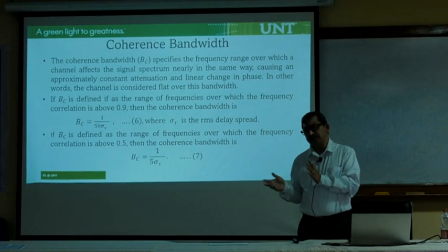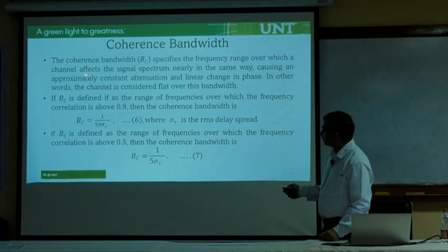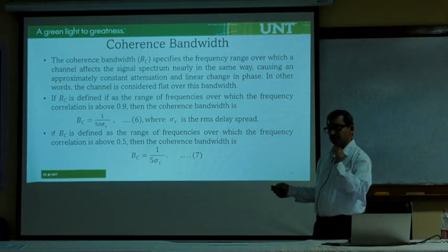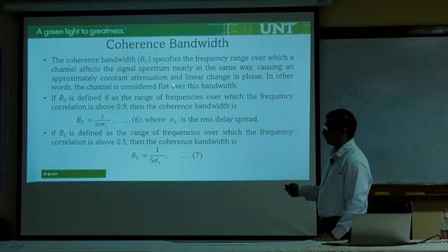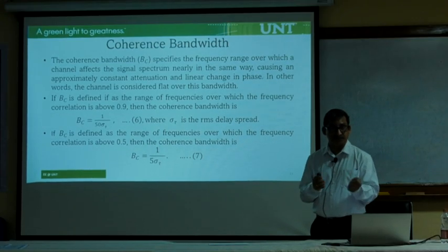The same way over frequency also, it behaves differently for different frequencies. So we are now asking, what is the bandwidth over which the channel behavior is going to be constant, and that is what we call flat. I hope you see the point. You need to understand the channel from both time and frequency sides.